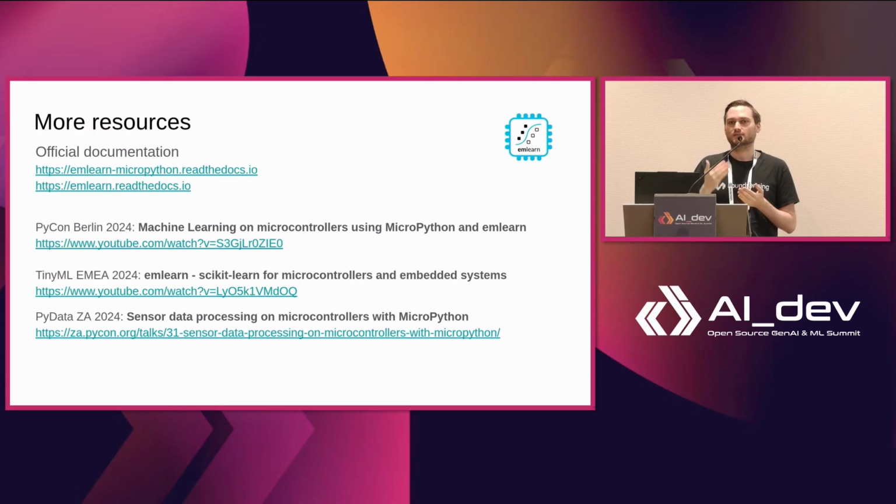But of course, if you don't have a good reason to go for a microcontroller, if you're in that area, it might be just easier to do it on a Raspberry Pi, a small embedded Linux type system. You can do it, but you should only do it if you need that power constraint, or you need the cost per device to be quite low. Otherwise, for image stuff, I would definitely consider going to an embedded Linux type device, or a phone if that can fit your use case.